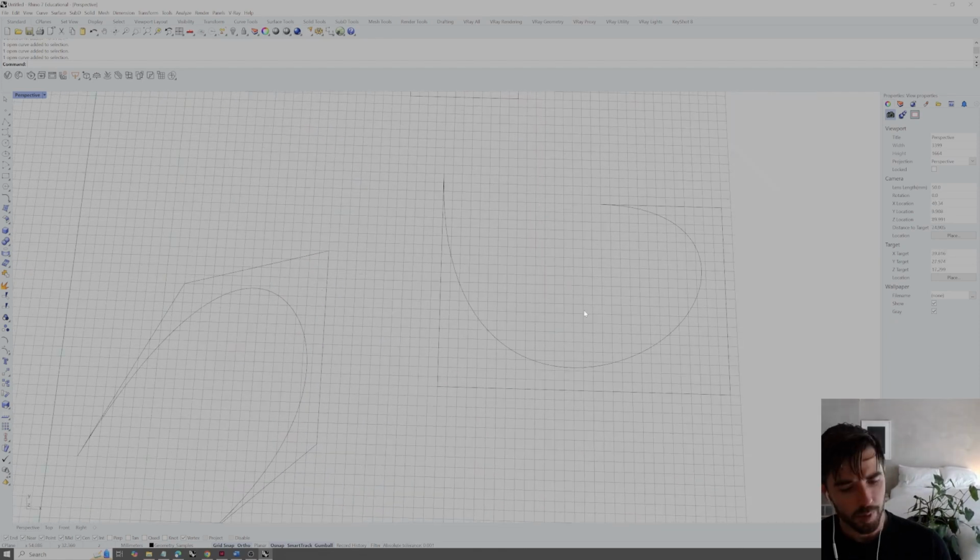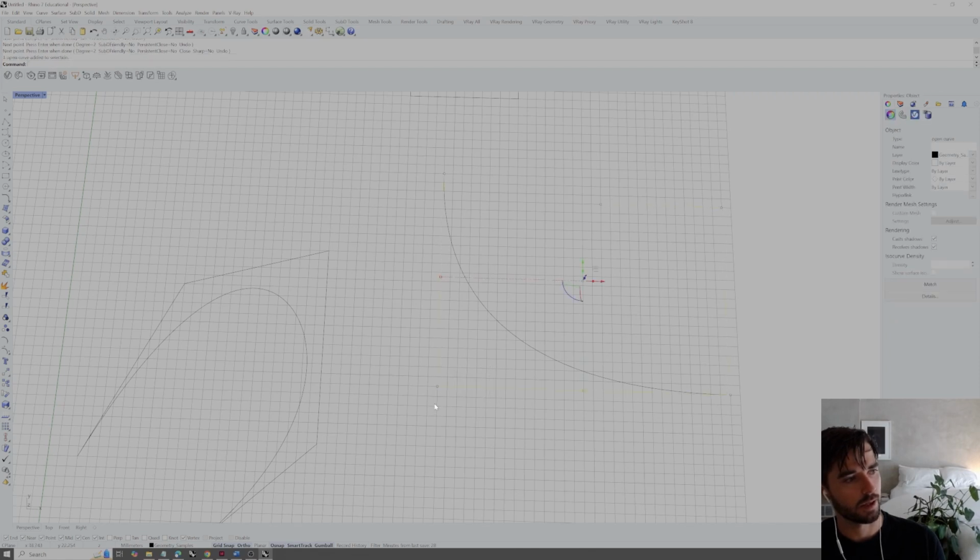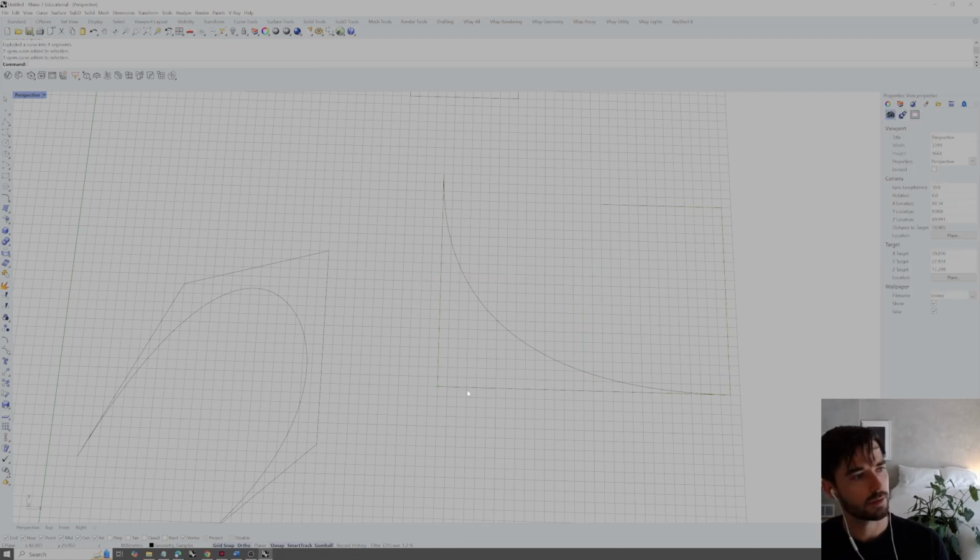So we can start by deleting this NURBS curve, typing curve again. I'm going to start by changing the degree to 2, and then I'm going to deposit a control point for this curve. We'll start by just doing it at those two segments of this polyline. Now, if I explode this polyline, we have each line segment divided into its own object.